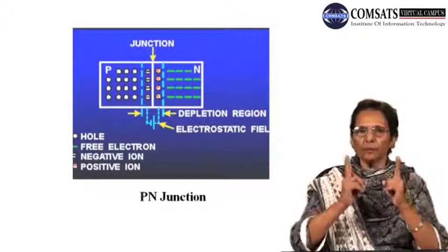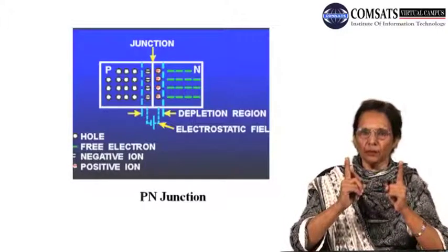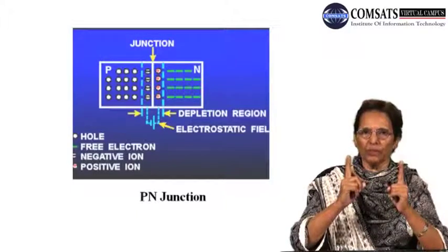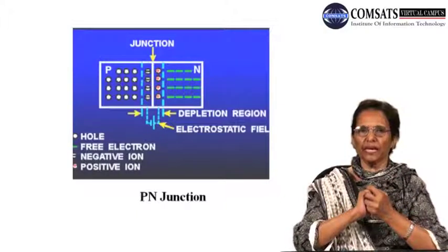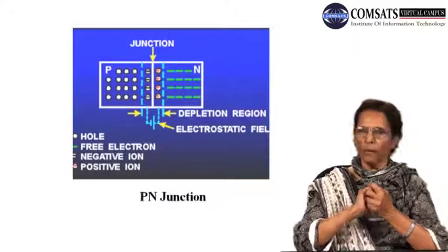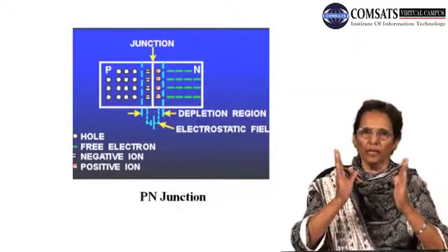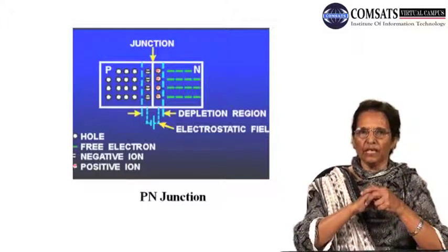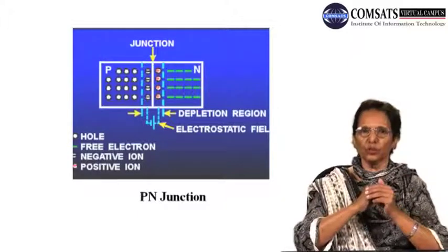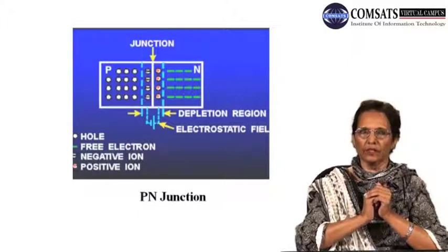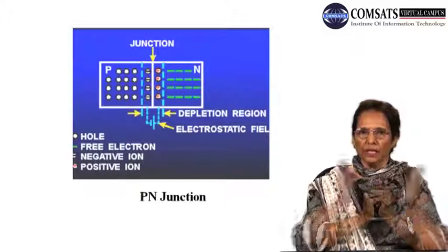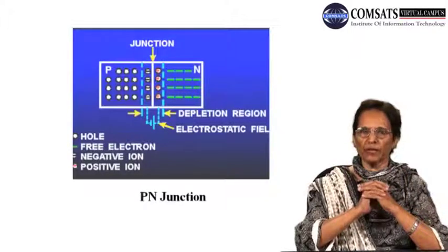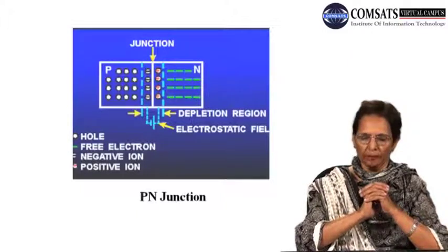The same depletion region, the same space charge region, has a depletion width designated by the letter W, which represents a region in which no free charge carriers can reside, because they will be swept away to the P and N regions by the built-in electric field that is established due to these uncompensated ionized donor and acceptor impurities. Hence a potential difference is established and an electric field comes into being.